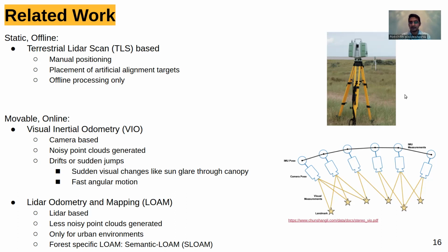In this case, I'm only adding factors. The LiDAR is working at 10 Hertz, while the IMU or the VIO outputs are coming in at 50 Hertz. And the IMU itself was working at 200 Hertz, but I was only adding factors whenever both the LiDAR scan and the VIO input were coming in. So essentially at a maximum of 10 Hertz and possibly slightly lesser than that.